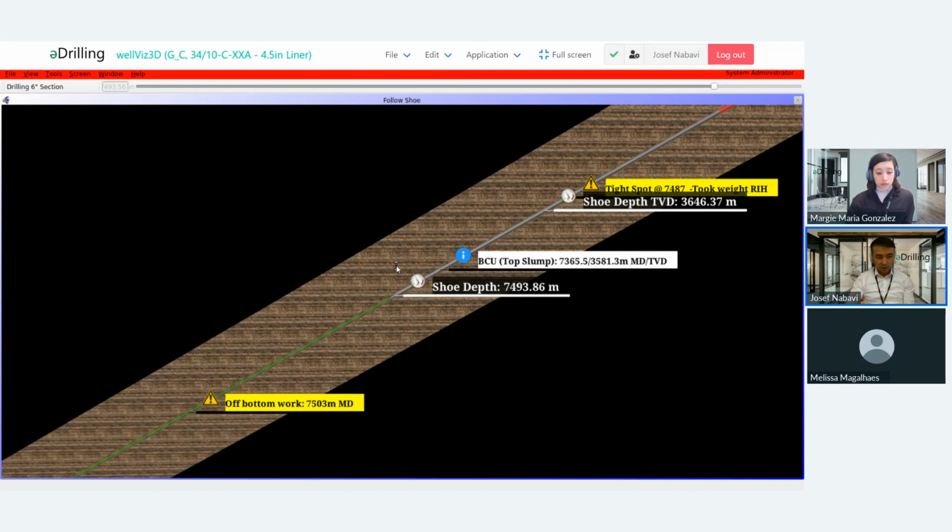As you are tripping in or tripping out, you see in front of you, upward or downward, okay, in this step I face this risk. I need to run hole a bit carefully through this area. Let's say that you have some shale formations, then you would like to be a bit more careful, and then you run slowly, or you have some other procedure. So you don't need to check other documents for where these steps are. You have everything in front of you.